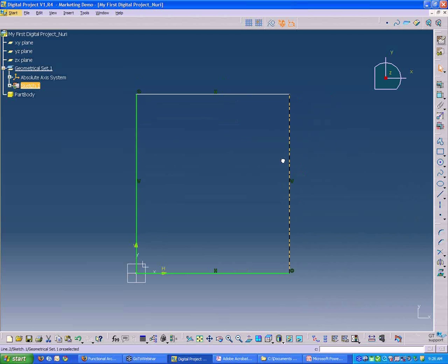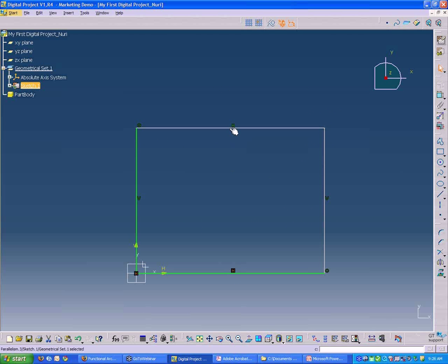As I drag and move this around, you see. And then I have 2 horizontal constraints, keeping these lines horizontal. And then I have 2 coincident constraints, and those are both linked to the different directions inside the sketch here.